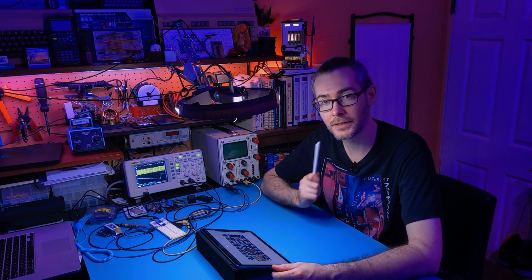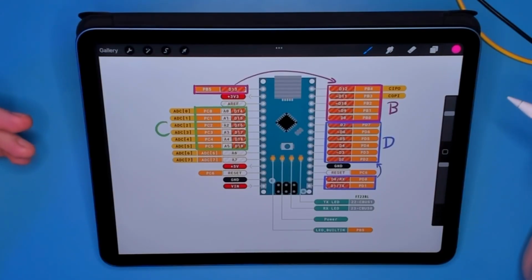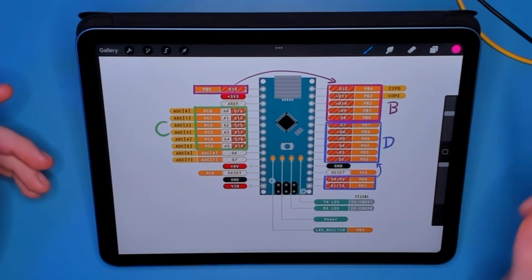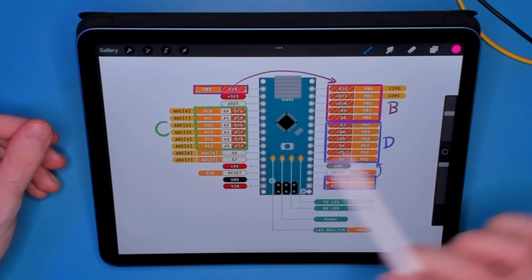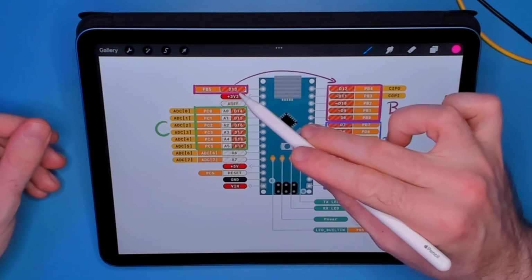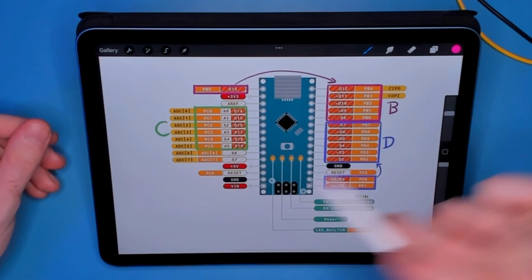Fortunately, AVR microcontrollers have an instruction aptly named OUT that can not only set up to 8 pins at the same time, but it does so in a single clock cycle. If you're counting, that would be hundreds of times faster than a bunch of digitalWrite calls would be. The pins just need to belong to the same GPIO port, and the Arduino Nano has 3 such ports named B, C, and D. Conveniently, the low 6 bits of ports B and C each map to 6 digital pins, Arduino pins 8 through 13 and 14 through 19.